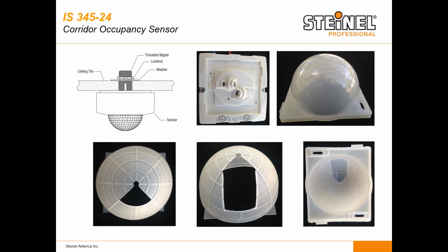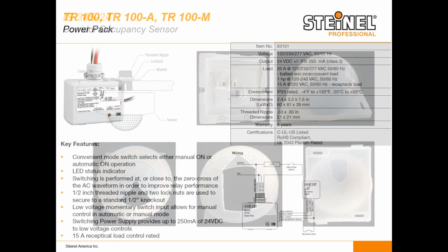But some of them, you need much more coverage. If you have a long aisle and it's not divided up into different tenant sections, this type of thing, then you'll cut a small section out of this. Whenever you cut the small little section, now it'll give you 33 feet of coverage in one direction, and it'll completely cut off the coverage that's back behind it. And then you place the little shroud inside the lens, you reinstall it, and it will only look in that one direction.